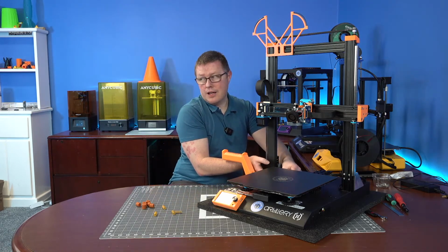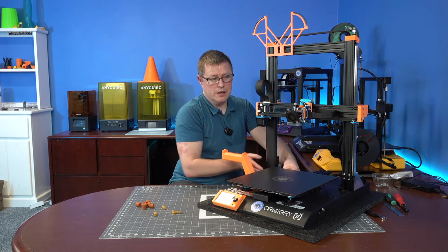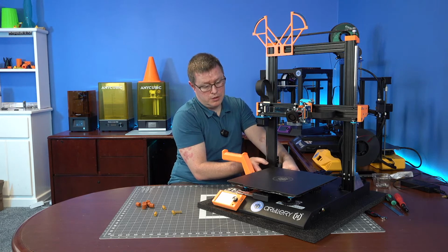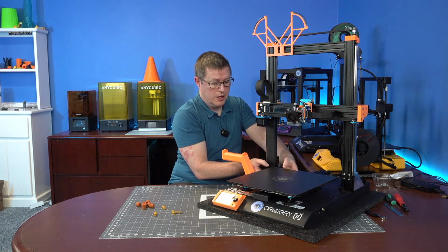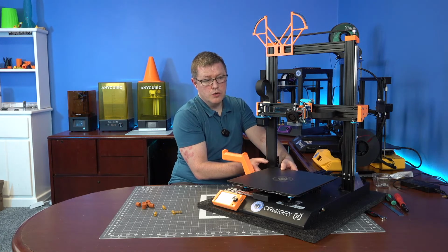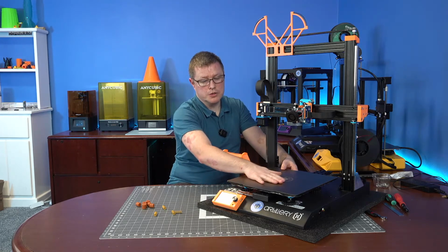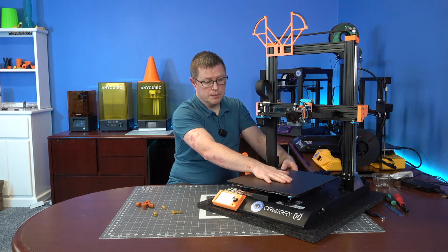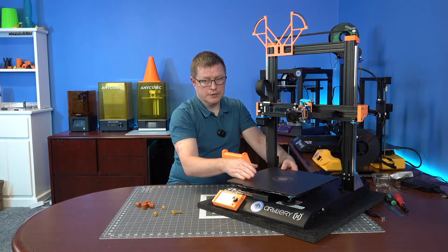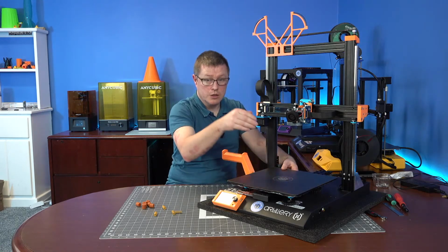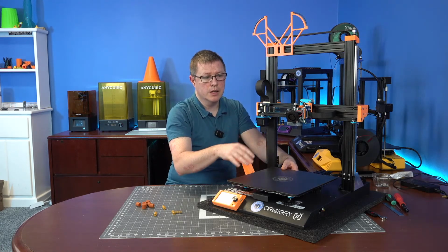So one thing I haven't done is perfectly dialed in the Z offset on this yet. If you have a printer that doesn't have a BL Touch and you add one and you're adjusting your Z offset, if your negative value is too low, it will continue to have 0 actually be below your build surface. So you do your initial homing, then you go to level your corners and it smashes the nozzle into the plate every time, even though you did it perfectly, and then you do it again and it does it again, because you keep moving the plate down.